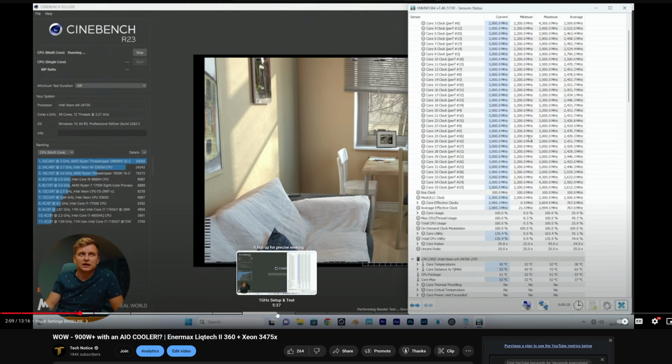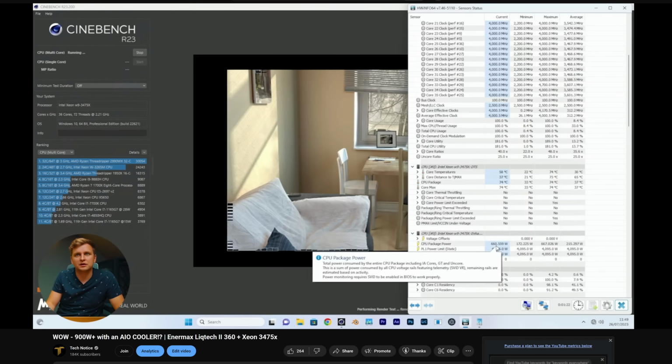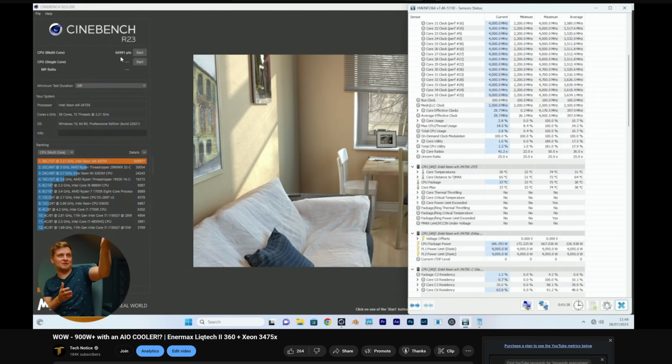My room temperature was quite high, which means I'm going to hit the thermal limit a bit higher. But we pushed it to 900 and something watts with this power supply. From the wall, this power supply was drawing over 1300 watts. This is an ATX 3.0 spec, and I don't know what the OPP is set for this one, but I was easily pulling 1300 watts, which is probably not what people should be doing at home, but we were able to do that.